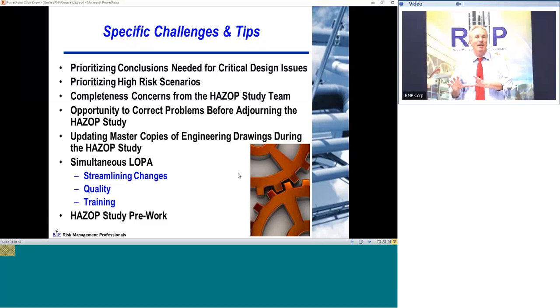Pre-work, being ready for the HAZOP, laying out, I like to do for major design efforts, make sure it's noted beforehand and also identify at least the key scenarios or key causal events that I want the team to look at so we don't miss anything. And it maintains a structure that's easy for me, as the facilitator, to find things if I'm working with them hand in hand in the design process and iteratively find things later, or when we turn over the product for them to do MOC.